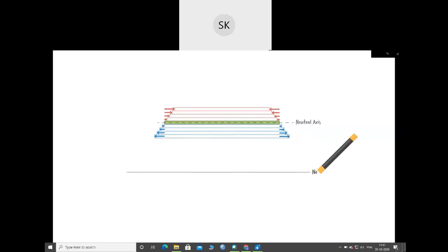Here are the forces present at the two ends of the segment. From the direction of the forces, it should be obvious that they want to cause a rotation. These forces want to turn the right vertical plane in the counterclockwise direction, and these forces want to turn the left vertical plane in the clockwise direction. We can argue that this rotational tendency is being caused by an internal force, which we call a bending moment.